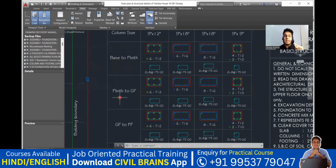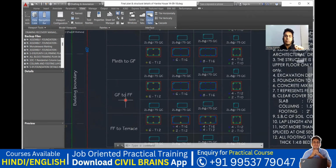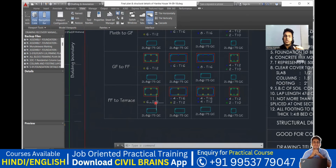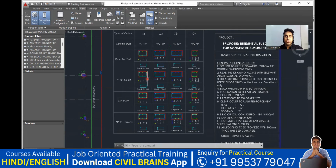Now when you come to the plinth, again the same thing will go on. Again from the plinth to the ground, again it's 12 diameter 6 bar, 12 diameter 6 from ground floor to first floor to terrace. Again you are providing 12 diameter 6 bar. So usually if you're putting a small structure like a ground plus 1, ground plus 2, we don't try to change the steel. Whatever steel we are giving, right from the base to the first floor or second floor, we take the same steel. So that is why if you see here, everywhere 12 of 6, 12 of 6, 12 of 6, 12 of 6.